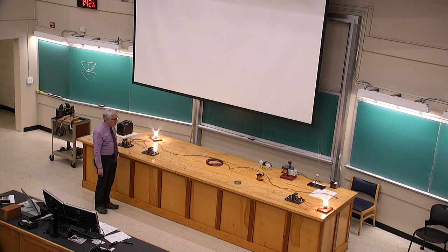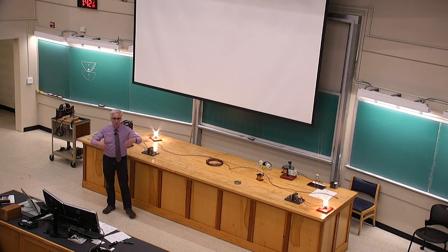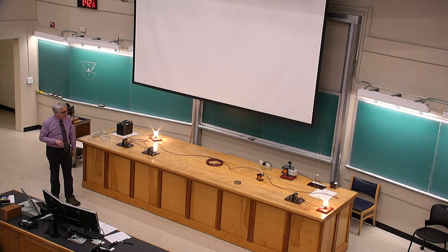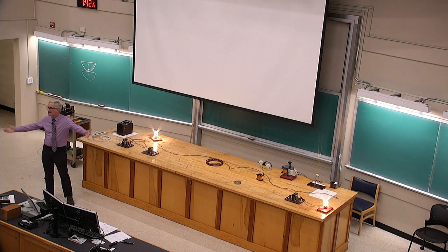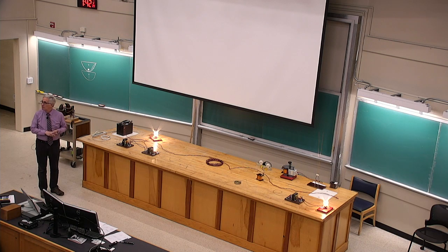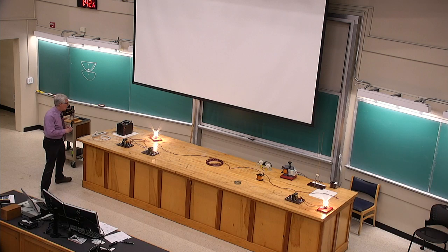So the current flowing in these wires now is reduced by maybe a factor of 10 or 20. As a result, the amount of push you need to get them to go through is reduced. The voltage drop in the wires is smaller because they're not carrying that much current. You don't have to push that hard. And so the wires aren't wasting as much electric power. Okay? So this is the whole scheme. Hopefully you can follow that.